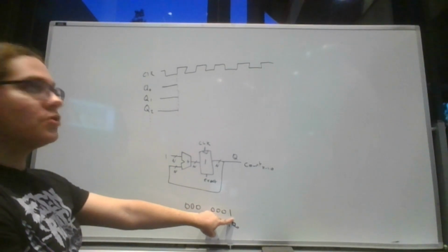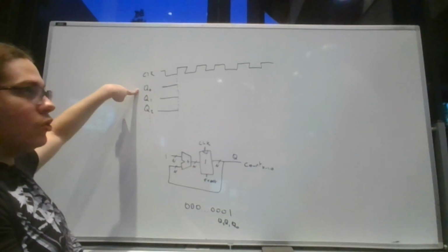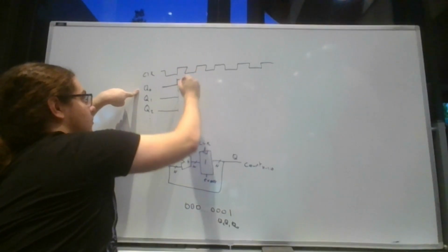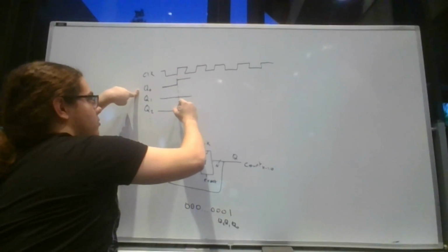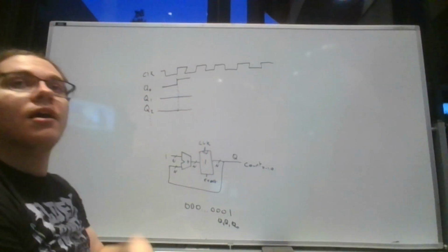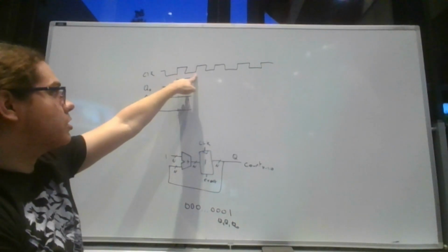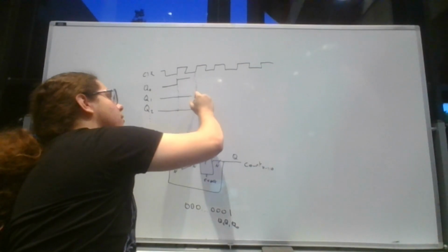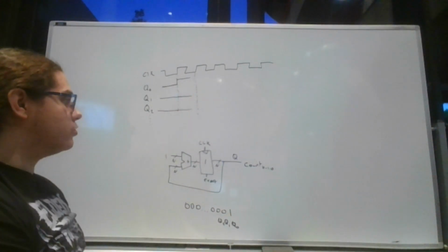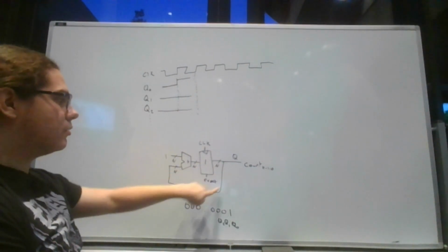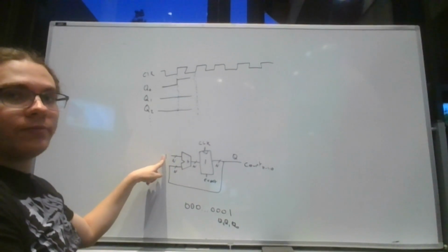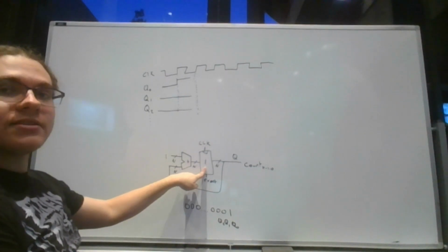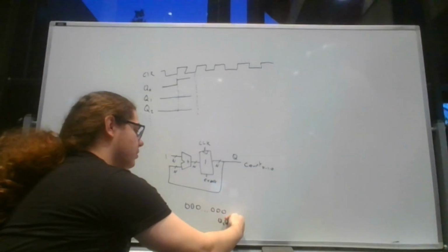So we just said this went up to a 1, which means that Q bit 0 has just gone up to a 1, whereas the rest of my bits remain zeros, until the next rising edge of my clock, which occurs here. At this next stage, we have 1 in the register being added with 1 on the other input of my adder. When I add them together, I get 2, and that's the next value that's going to be stored into my register.